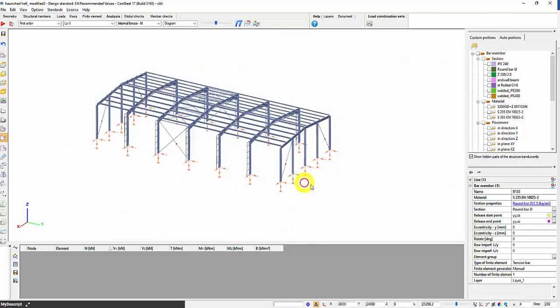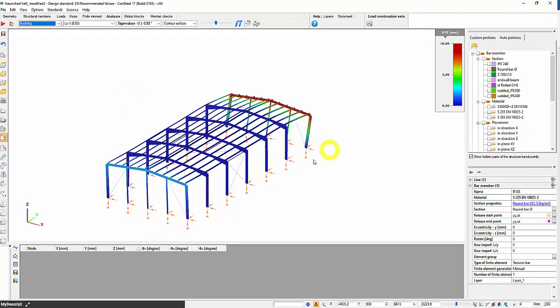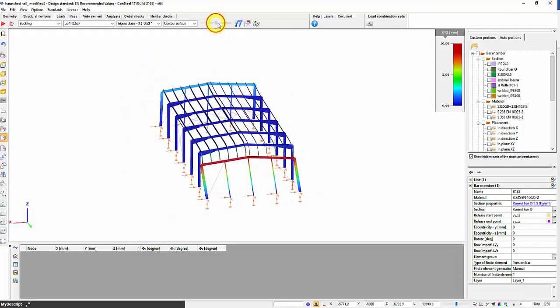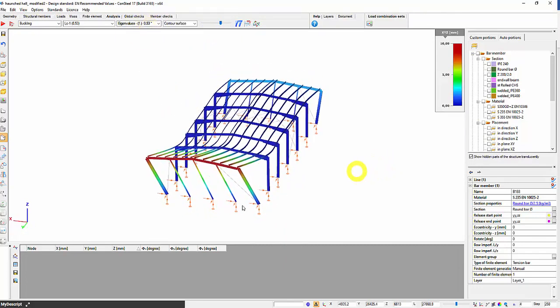In this case, there is no problem because they don't contribute much to the planar stiffness, but if there is also a stability result, since these bracings no longer exist, we get an unrealistic shape for loss of stability, with a very low critical load factor. In practice, one of the rods will be in tension in this case, so this shape in reality cannot happen.